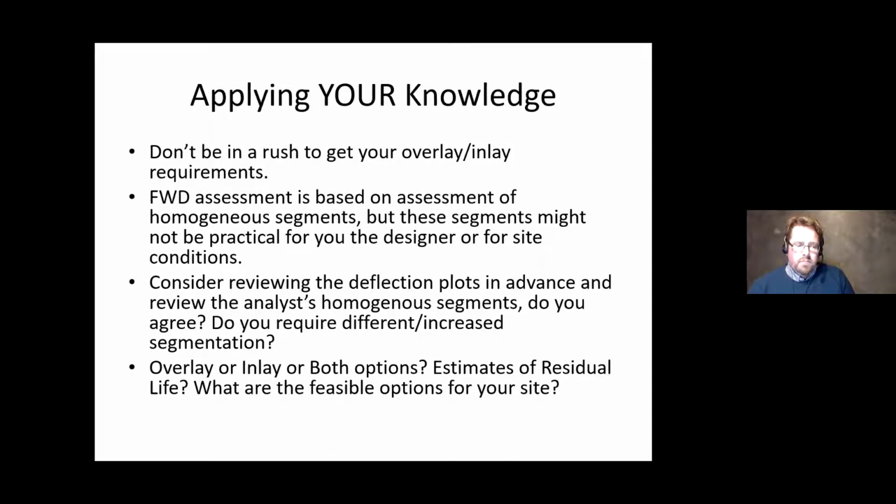If your existing pavement is structurally adequate, you might need to do a rehabilitation based on an inlay. Find out what your inlay requirements are. It's very easy to make it part of the tender and get it carried out at the time, as opposed to realizing afterwards you have to go get the testing done and have to re-tender.